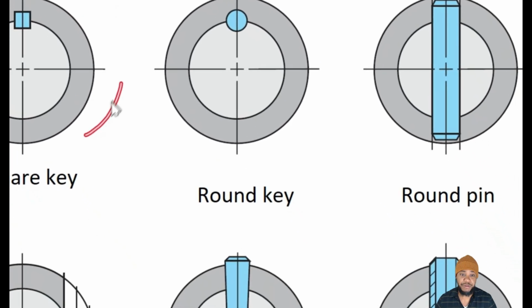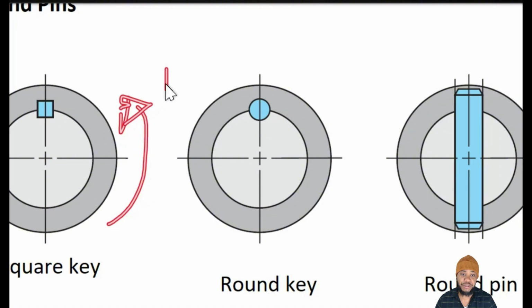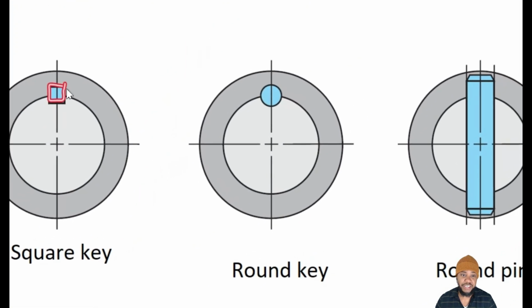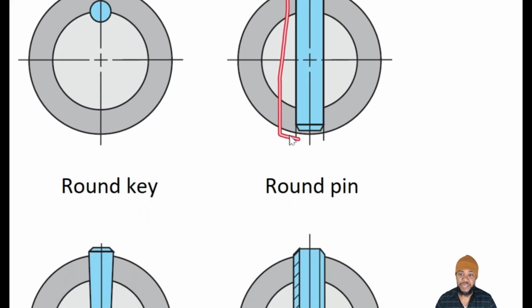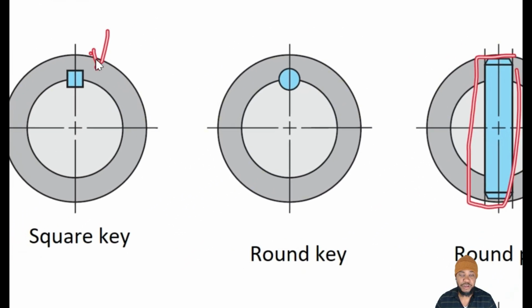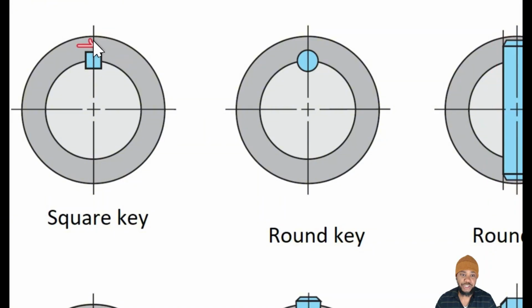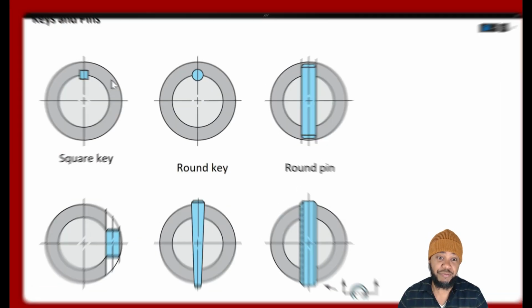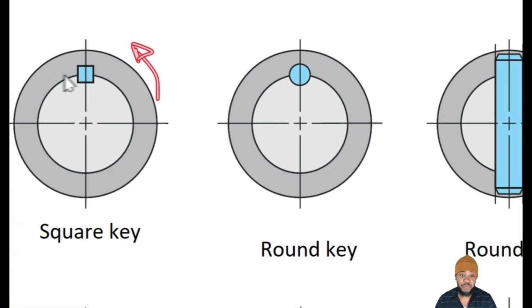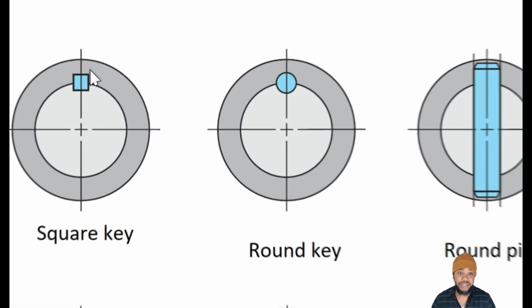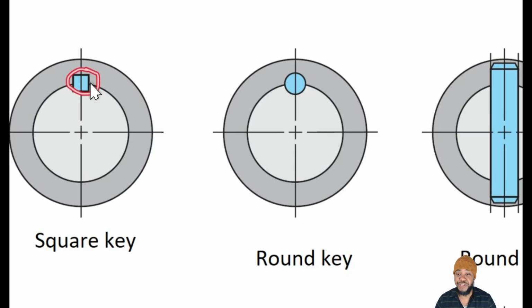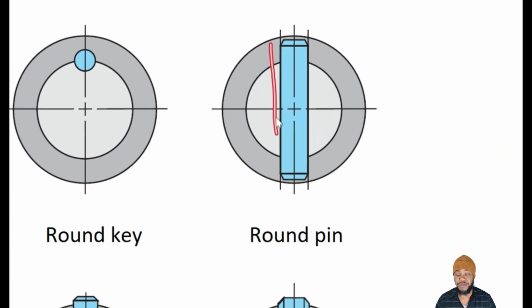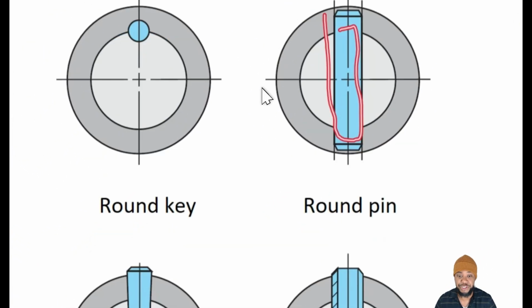To interface them and to transmit torque between them, we introduce a key or a pin which interconnects both of those shafts and over which shear stress develops, direct shear develops in the transmission of that torque, right? Based on that idea, the key often becomes the region of failure because it has a very small cross-sectional area, where the pin as well becomes a critical region.